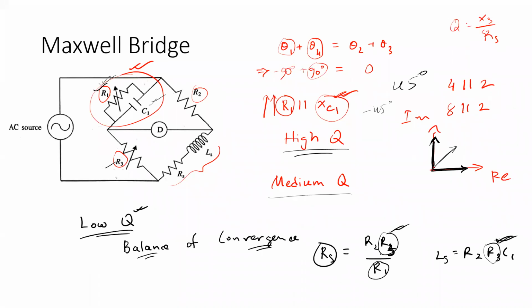So several trials have to be done in terms of R3 and R1 to find the optimum case where there will be almost zero deflection in the bridge. So tuning both the resistors to obtain the null deflection becomes a problem in case of measuring inductances of low quality factor using this particular bridge circuit.